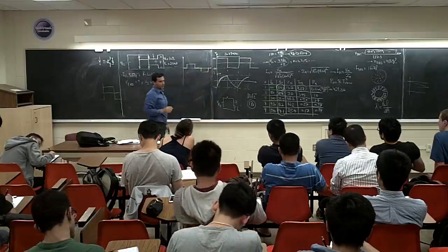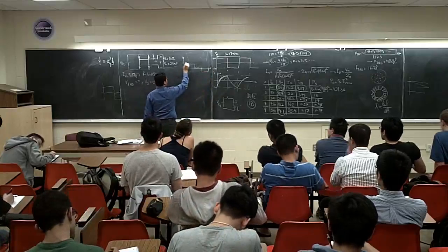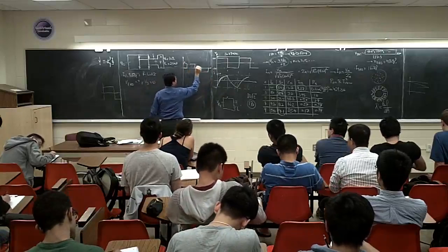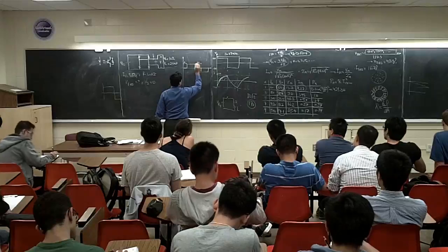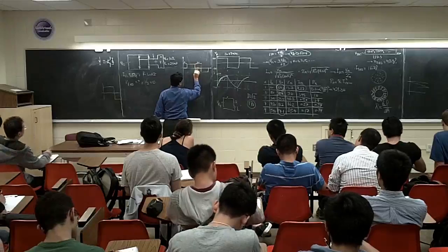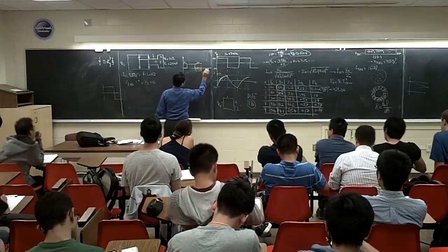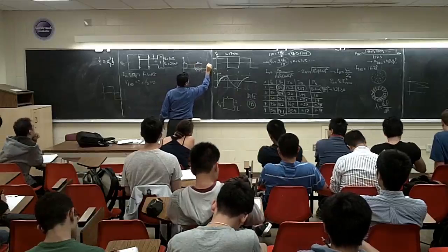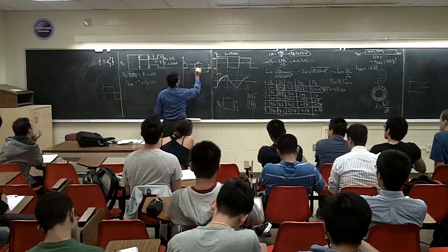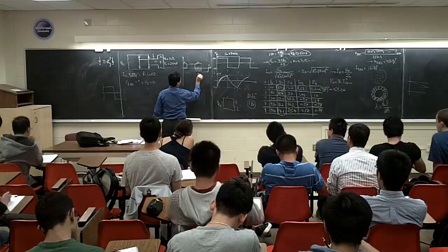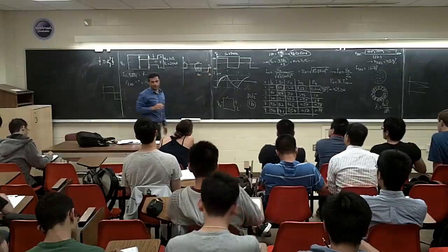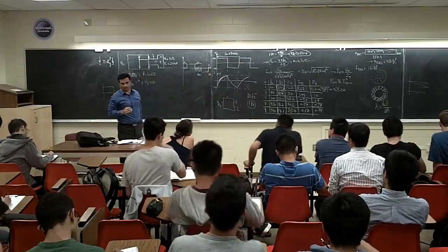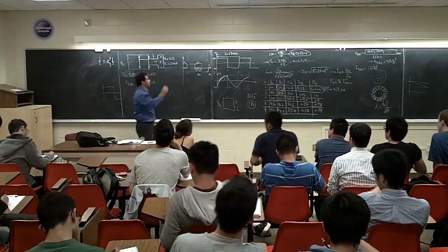This is one cycle I put together, right? This is the alpha. This is the 2 alpha, right? And this is again alpha, alpha, alpha. And this one is 180 degrees, and this is 360. This is one cycle. The output voltage waveform is like this, with the harmonic elimination.